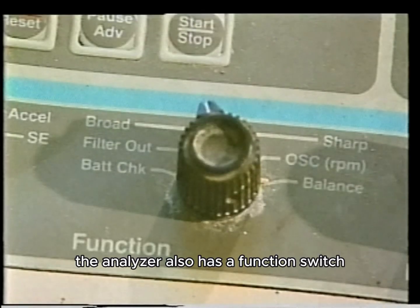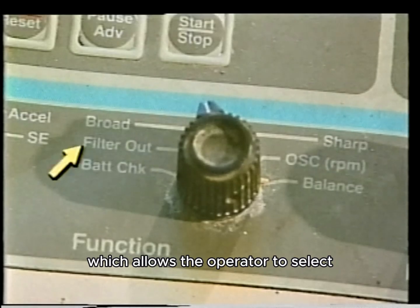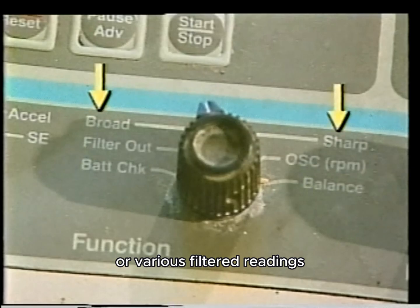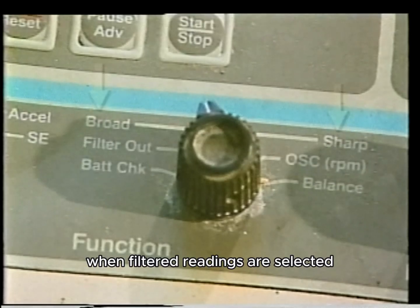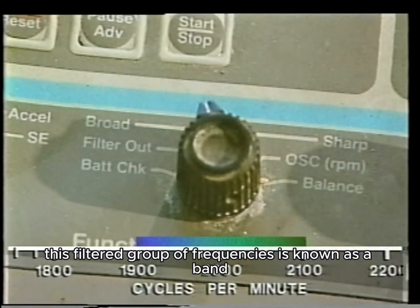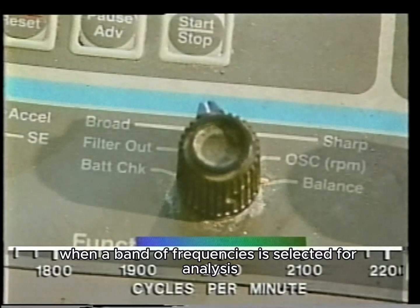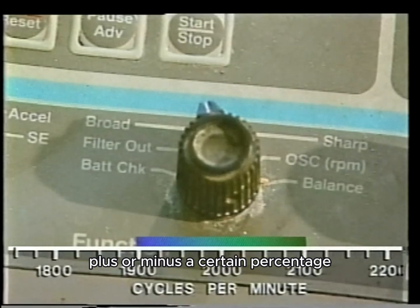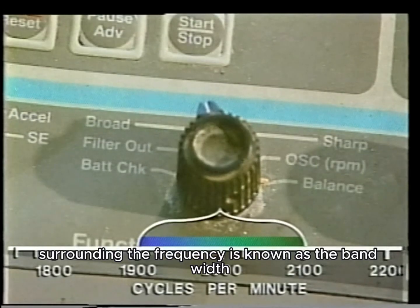The analyzer also has a function switch, which allows the operator to select overall vibration readings or various filtered readings. When filtered readings are selected, the analyzer examines a certain group of frequencies. This filtered group of frequencies is known as a band. When a band of frequencies is selected for analysis, an analyzer will examine the frequency plus or minus a certain percentage. The total area surrounding the frequency is known as the bandwidth.